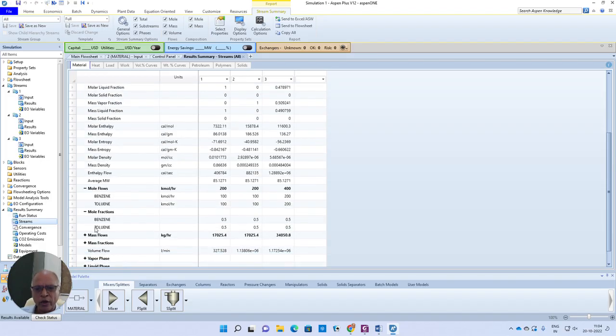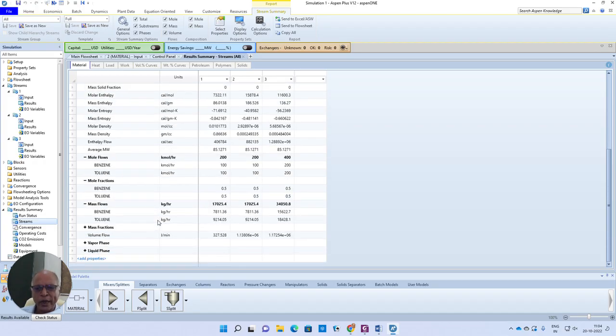In the same way, we will also be able to identify the mass flow. Though we gave the mole flow rate, how do you think this mass flow rate is calculated? We may need density, which is calculated here. So using the density, it will be converting the molar flow rate into mass flow rate. And the mass flow rates are both equal because the compositions are equal. This is the total mass, and these are the moles, mass of each component.